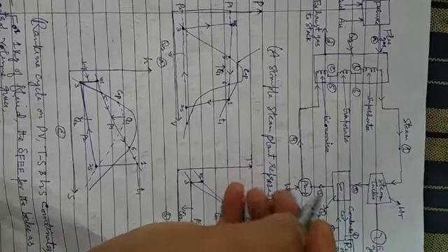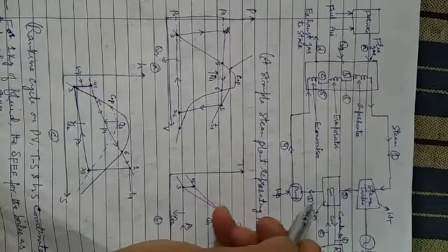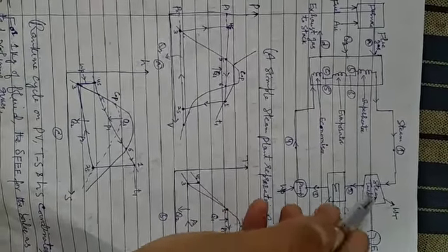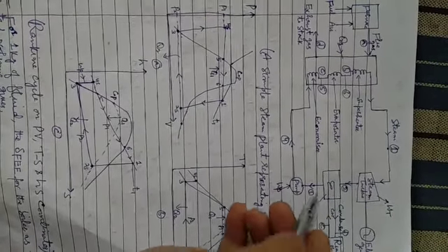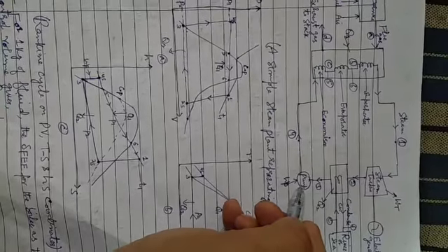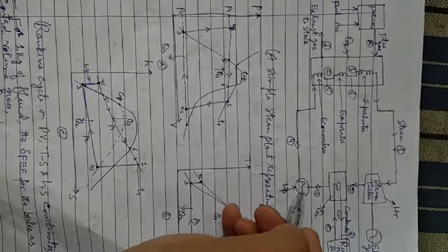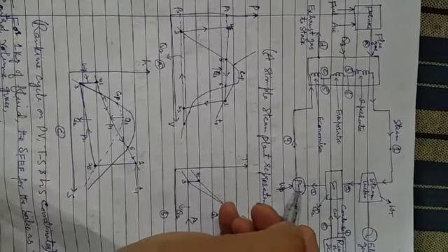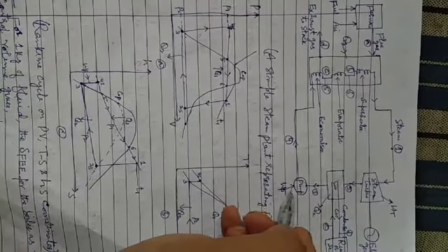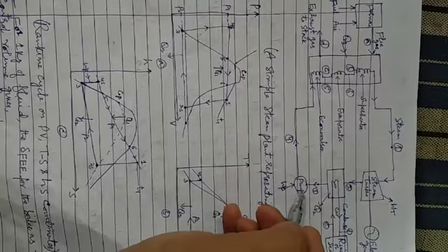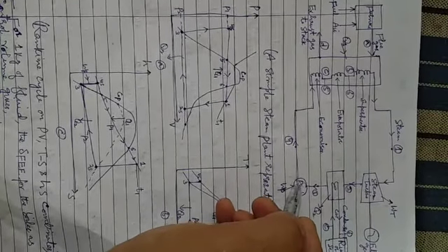There are two types of work done in this steam power plant. One is the work done by the steam turbine. The second is the work done on the pump. Since the pump uses electrical energy to do work, it is work done on the system, not by the system, so it is a negative work.